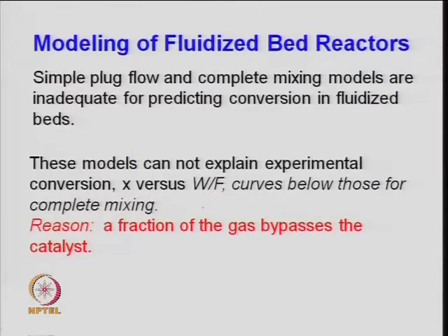When you do the modeling or design this kind of fluidized bed reactor, I am not going into detail because that is a chapter's course, but very quickly I will give you a glimpse of the approach to design it, right. Modeling of the fluidized bed reactor involves hydrodynamics, and something used to find out the overall rate of reaction or the resistance offered. So, simplest, as I said, is a combination of plug flow and a CSTR.